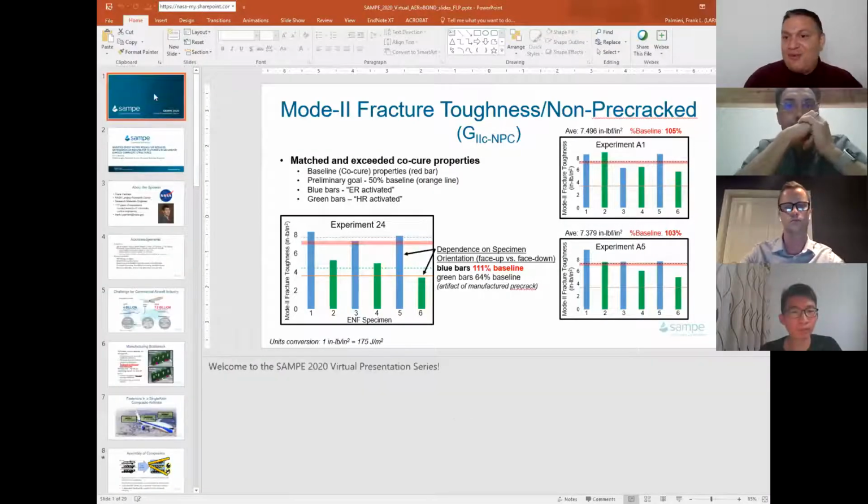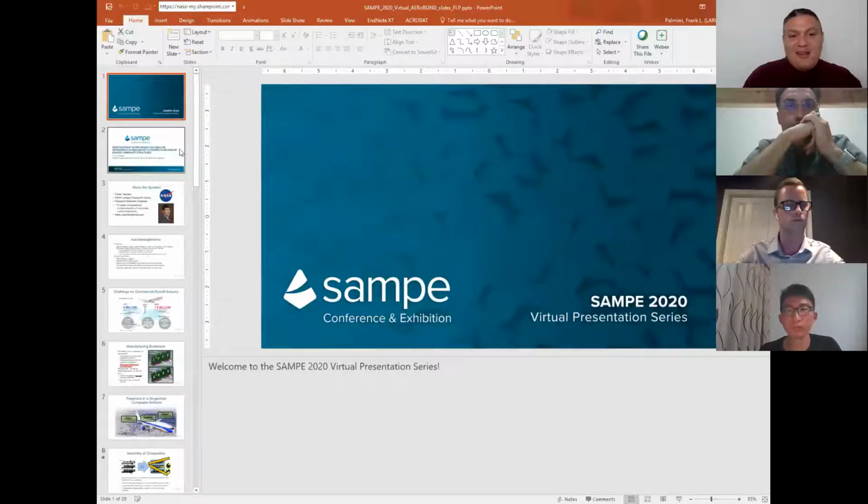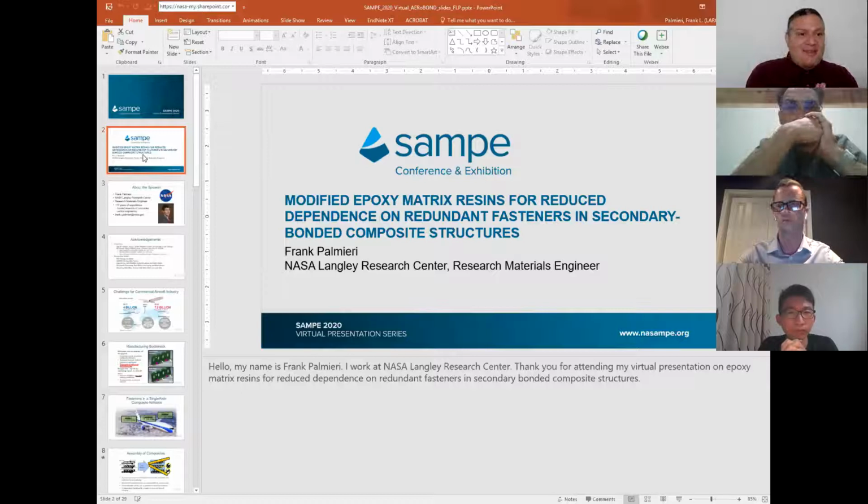Thank you so much for this discussion, Frank and Peter. So, Frank, I'm going to switch to you and we're going to start talking together. So first of all, I want to verify that I understood your paper the right way. Your work, you're looking into getting rid of adhesives and trying to come up with new resin system, where the resin system actually is what, when you're doing secondary bonding or follow-on processes, it's the system that will actually diffuse and will actually act as the adhesive in order to generate adhesive-free bonding. Did I understand your paper right?